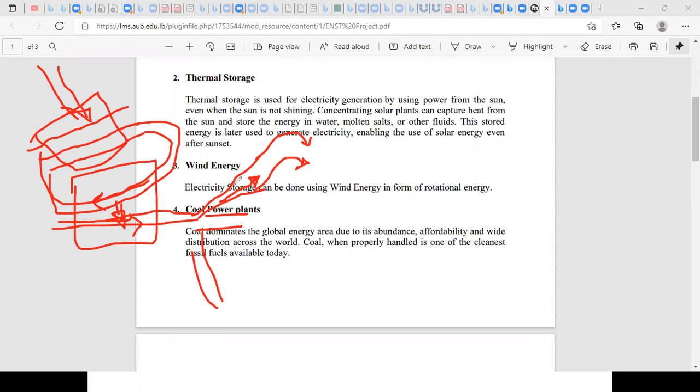If you are in hours where we don't have a lot of occupancy and we don't need a high flow rate of hot water to circulate in the space, then we can have a control system, or valves that can open and close to switch the path of water. So when you don't need this hot water, you can take it through another path, for example to a reservoir that will store this water until needed.